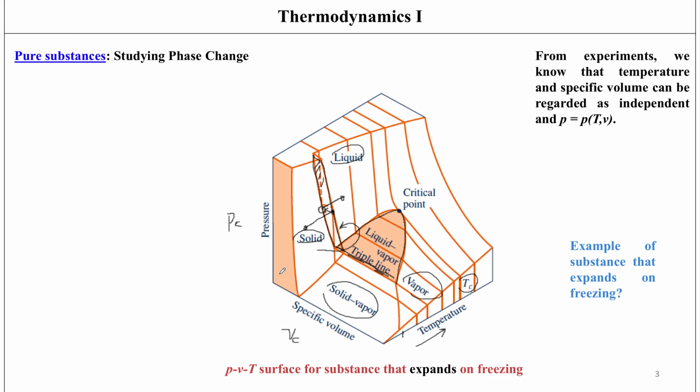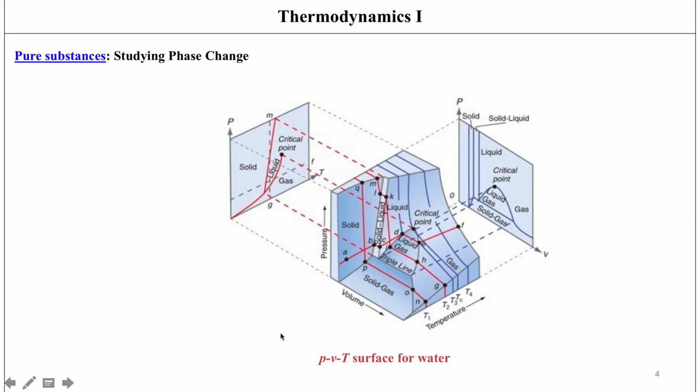If I was to, let's say, look at the projection in terms of the pressure and in terms of the temperature, then I should be looking at it from this side. Okay, and then I can trace all of these from this side. And if I was to look at the pressure and specific volume, then I would have to look at this PVT surface from this side. So instead of doing that, what we do is, let's say, we take the projections onto a plane, and it's easier to do that. It's easier to work with these then.